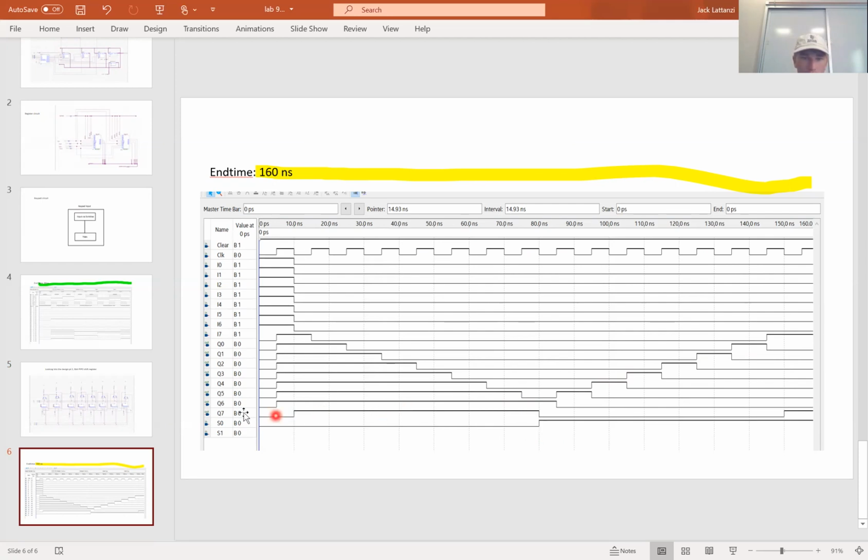So you can see this happening here because these are the functions right here. So 0, 0 is the enter one. Then 0, 1 is a shift to the left, so there's 7 shifts to the left. 1, 0 is a shift to the right, so these are all shifts to the right. And then finally at the very end, it's 1, 1, and there's a hold value here.